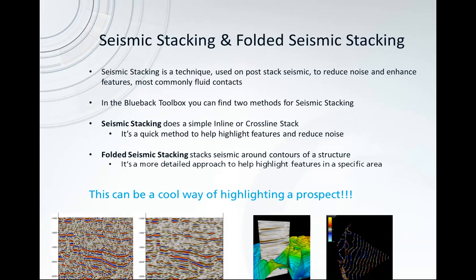So, seismic stacking in the context of Blueback Toolbox is a technique used on post-stack seismic to help reduce noise and enhance features, most commonly fluid contacts. In the Blueback Toolbox you can find two methods for seismic stacking. The first is a simple inline or crossline stack, which is a really quick method to help highlight features and reduce noise.